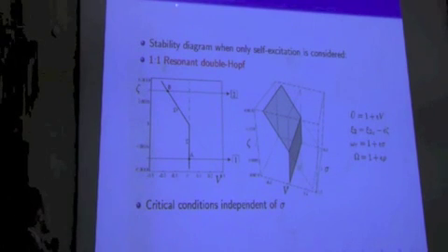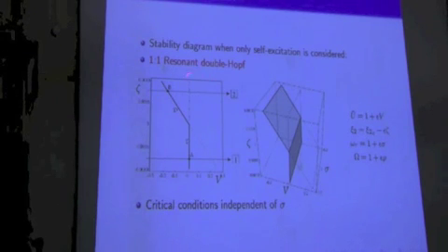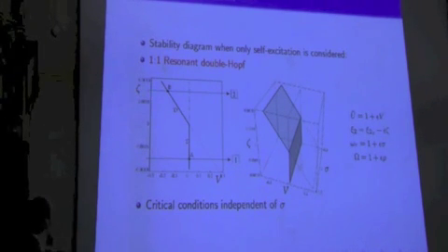We can study the solution, for example, just when we apply self-excitation. It means that we drop out the turbulence here. And we can see the stability diagram for the trivial solution in terms of the steady part of the wind velocity and the tuning, damping ratio here.